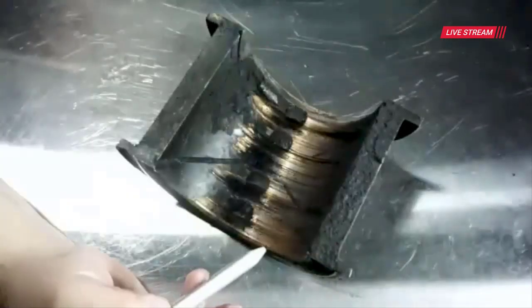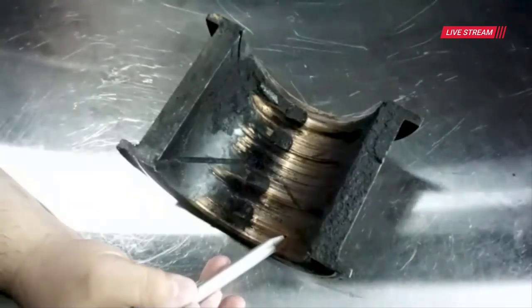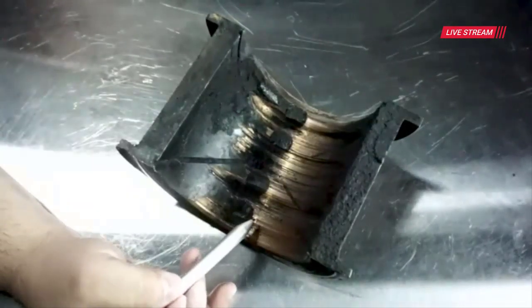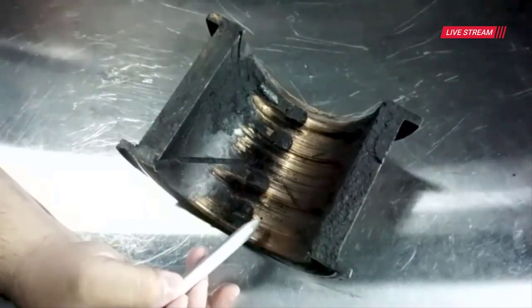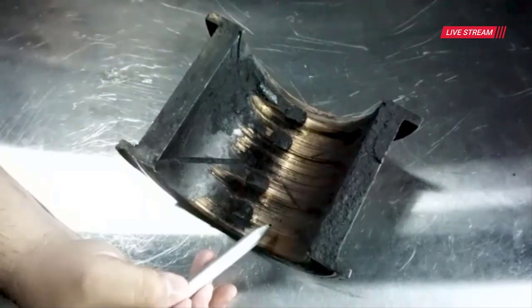An exaggerated example of this is a failed bearing that I've got over here. So if you're looking at this bearing surface, you'll actually see these raceways, the scoring in the bearing surface itself. This is where you've had particles that got in here and started to cut and gouge and remove that material over time. So as this builds up, as those particles get more and more embedded in there, it removes more and more material. And this is what subsequently leads to misalignment, failure, all these other associated things with particle contamination.